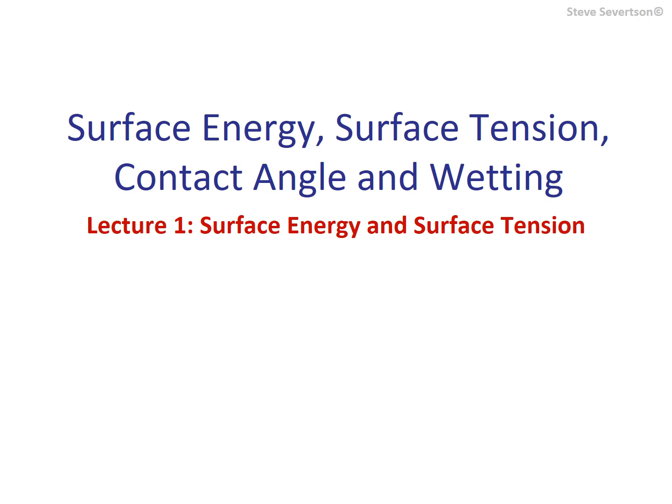A more detailed thermodynamic analysis provides the basis for a useful predictive expression for interfacial energies, utilizing surface energy values for the pure components composing the interface. The second half of the lecture focuses on the mechanical description of surface forces, or surface tension. Using the surface tension description greatly simplifies explanations for how various test methods gauge its magnitude.